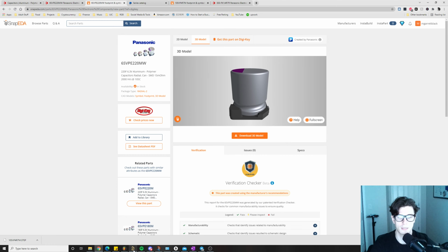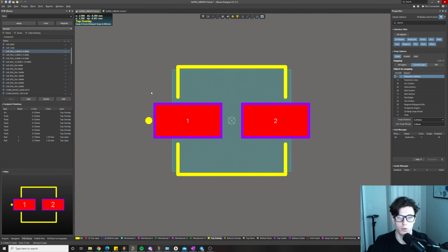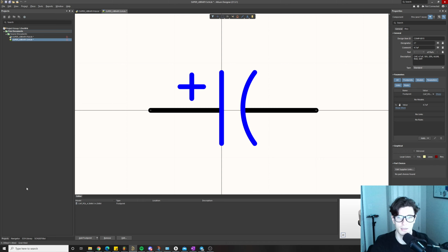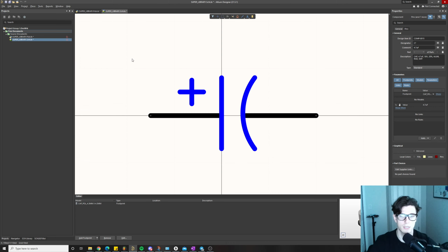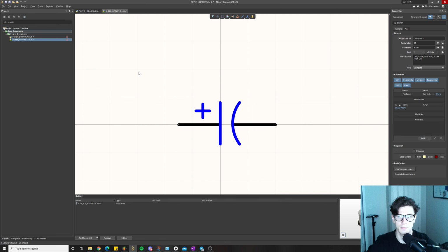And then the whole process is the exact same, where you draw your pads, you make your little overlay, you add your 3D model, and then you do the same exact thing in the schematic portion, right? This time, now that you already made one, you can just do a quick Control-C, Control-V.